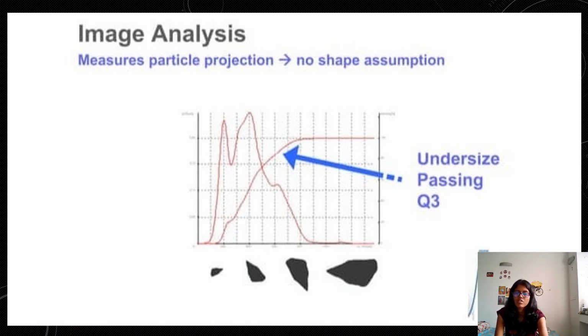Also, the curves could show a monodisperse curve. If a number-based distribution curve is there, then that could be a monodisperse curve, which will have a sharp peak, and a polydisperse curve, which will have a broad or multiple peaks, showing a wide range of particle sizes or multiple size populations. Multimodal distributions with several distinct peaks suggest the presence of different groups of particles, each with its own size range. If it is a volume or area-based distribution curve, then they emphasize larger particles basically.